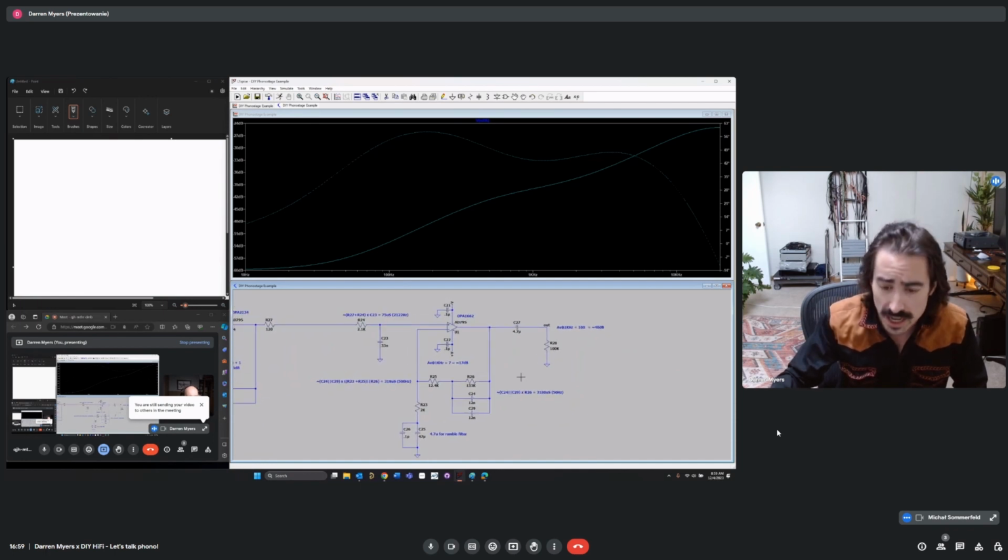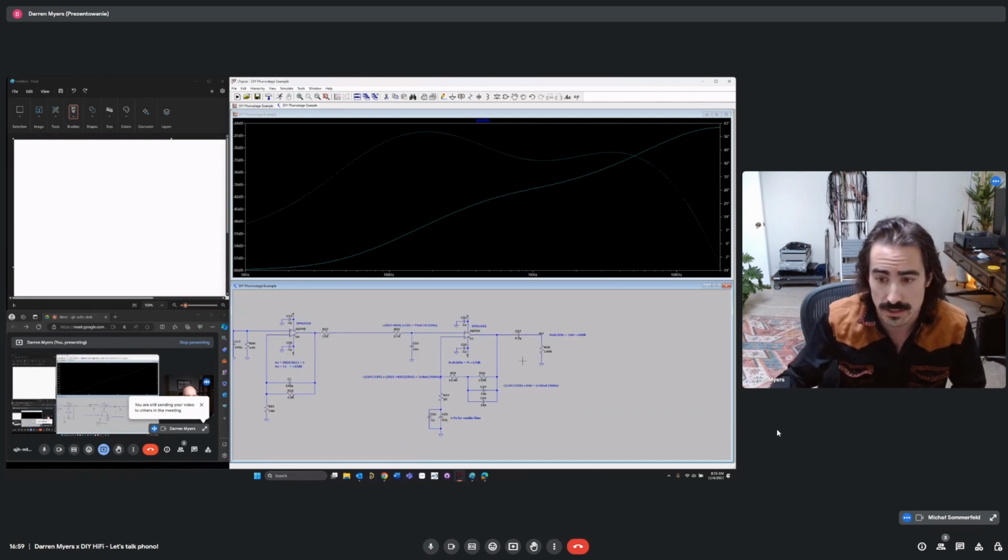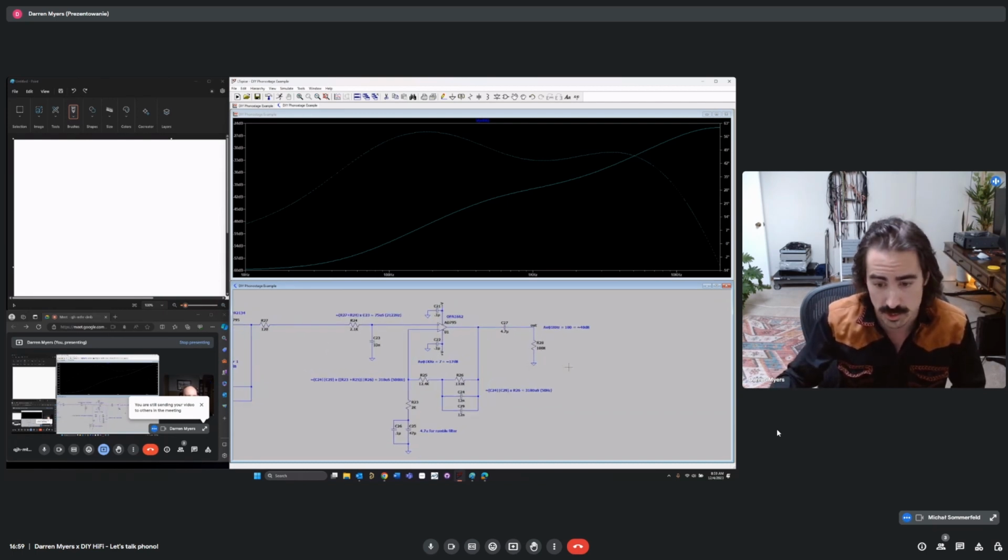And so for DIY stages, I do recommend using capacitors to reduce the worry of running into DC problems, because once you run into DC problems, it can be a bugger to fix without some redesign of your circuit.